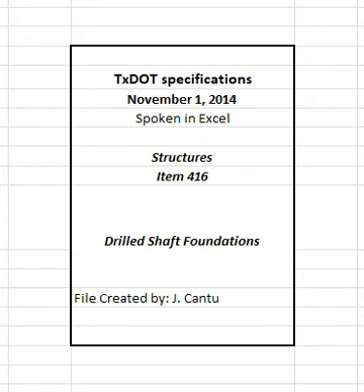Adjust the bottom of the shaft or alter the foundation if satisfactory founding material is not encountered at plan elevation, as approved to satisfactorily comply with design requirements. Blasting is not allowed for excavations. Stop drilling if caving conditions are encountered, and adopt a construction method that stabilizes the shaft walls.